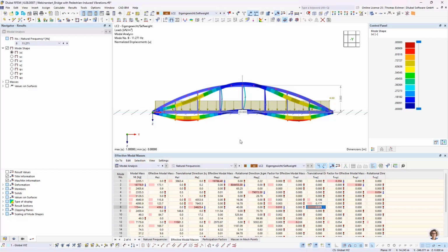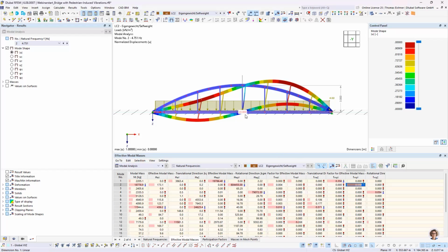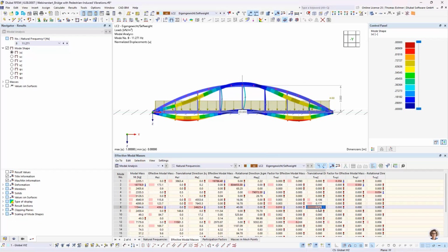Let's also assume, for an example, in this case, we have a walker that walks over that bridge, but we try to perform the analysis by simplifying it and putting him just on the middle load. Well, then the results could also be not so trustworthy, in my opinion, since, let's look at the second eigenform, we have no impact of this eigenform for a loading in the middle, and also with the biggest eigenform of the z direction, we also have no impact on this middle form.